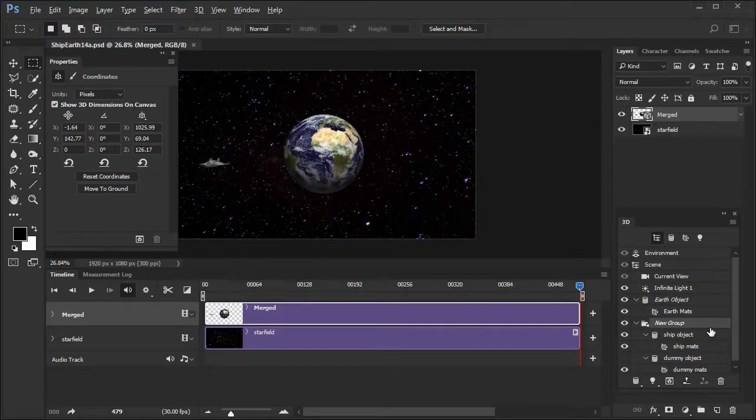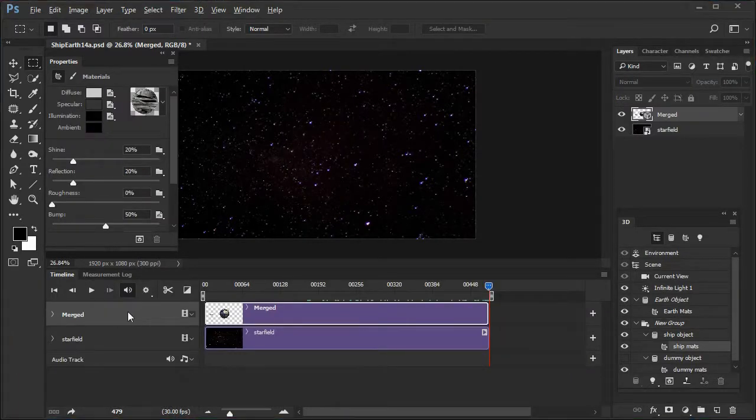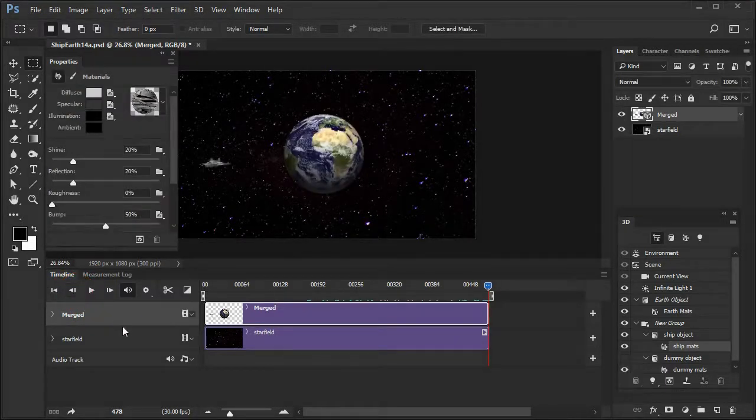So what will happen if we loop these tracks is that the animation will seem to pause at the end before looping back to the beginning, as both the beginning and the end are set to 0, 0, 0 degrees. The solution is to not render the last frame or to remove the last frame. To remove the last frame on both tracks, press the left arrow key or the Move to Previous Frame button once to move the playhead to frame 478.